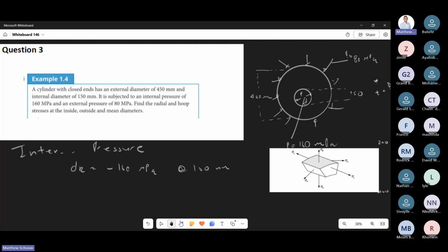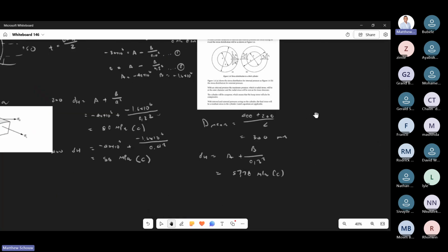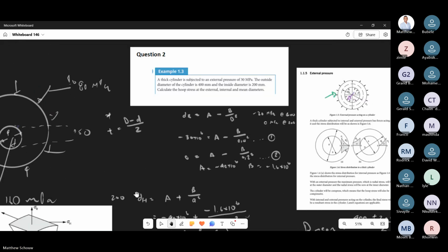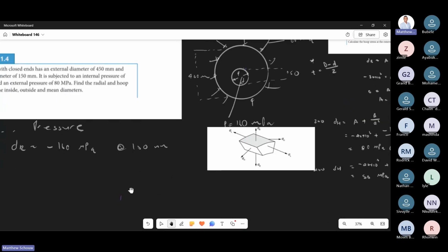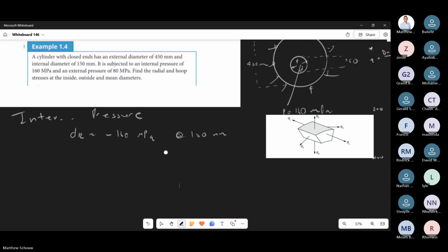So we're aware for the internal, like I mentioned to you. When you look at the internal side, we know that the radial stress is a maximum on the inner. Am I right? Is it on the inner? And then it becomes 0 on the outer. Am I right? Keep on forgetting. Yeah. And then this will be 0 MPa at 450. Okay.